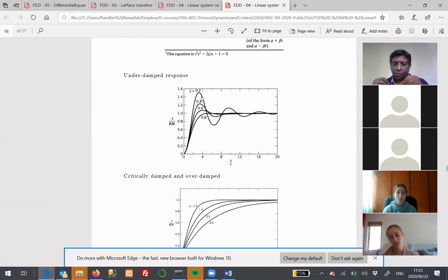So as we use higher values of Kp, as you use increasing values of Kp, your solution will oscillate more strongly. Because remember, Kp tells us how quickly our system will respond to a non-zero error. So if there's even a moderate difference between your set point and your current value, and you have a very high Kp value, then the control action is going to be very strong.